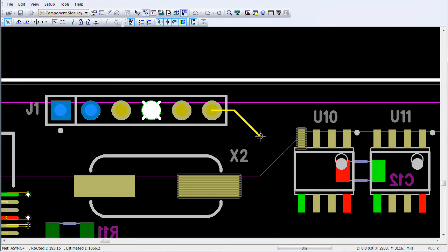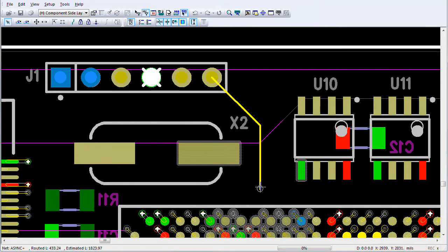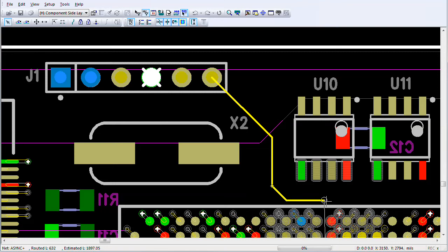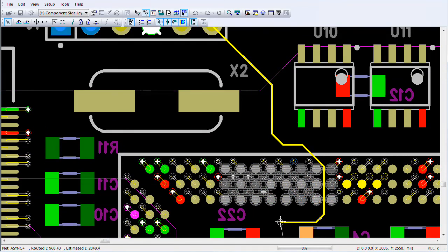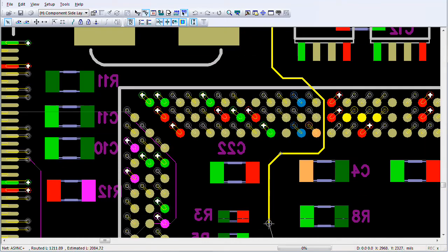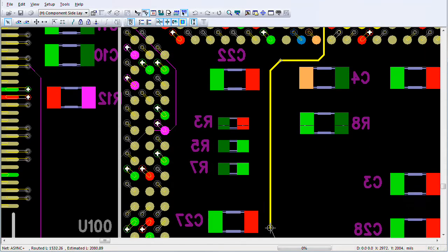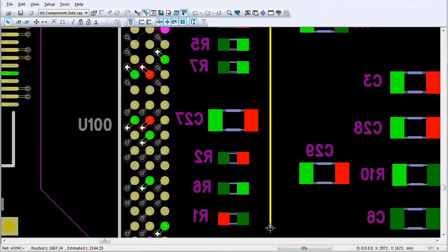As I begin routing a trace, note that a visible barrier appears around the surrounding objects in the color I selected previously on the Colors page. This band or barrier visually depicts the minimum clearance area. Its width and placement corresponds to the clearance settings defined on the Clearance tab of the Properties window for the various objects.